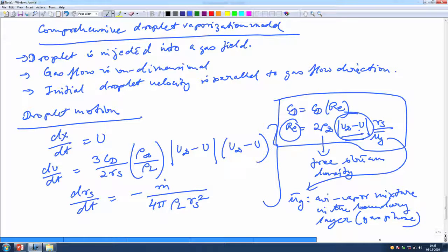When that happens, this Reynolds number is supposed to die down very quickly. So, you can expect a profile in which the Reynolds number goes down; that is what you get from this analysis. The care taken is that you compute the viscosity in the boundary layer, whereas you take the density in the free stream.